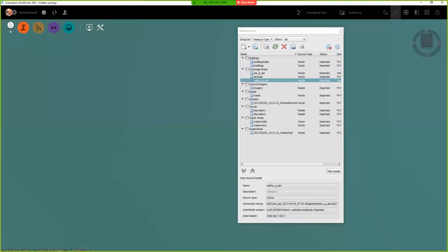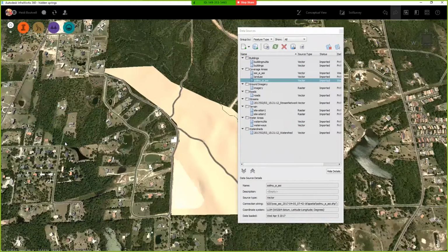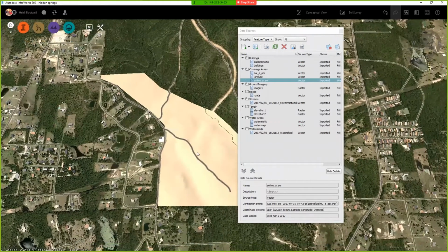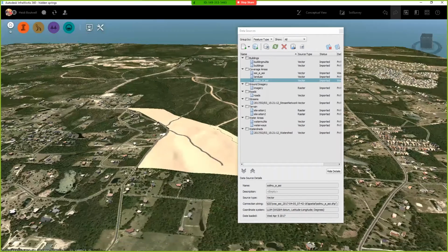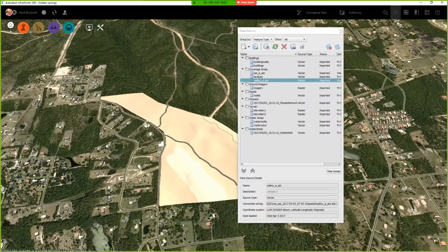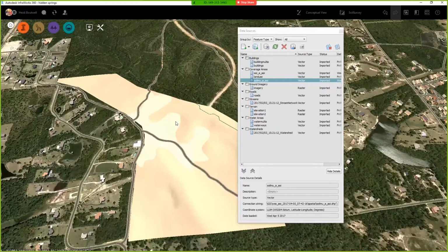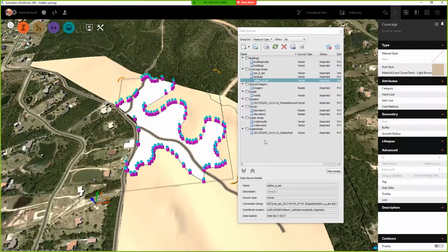And this should drape over, and it'll regen, and it may take a minute or so, depending on how fast your computer is, and there it is. So it instantly brings in a shapefile and covers my original. So that's the entire, okay, so the whole thing is soil anyway. That's real helpful, right? But you can see it's got different soil. What's interesting is my soil survey, when I took it, it showed all these funny looking shapes that you see lighting up. I can select a shape, and I can specifically just change the color of this one shape. That way it looks different.